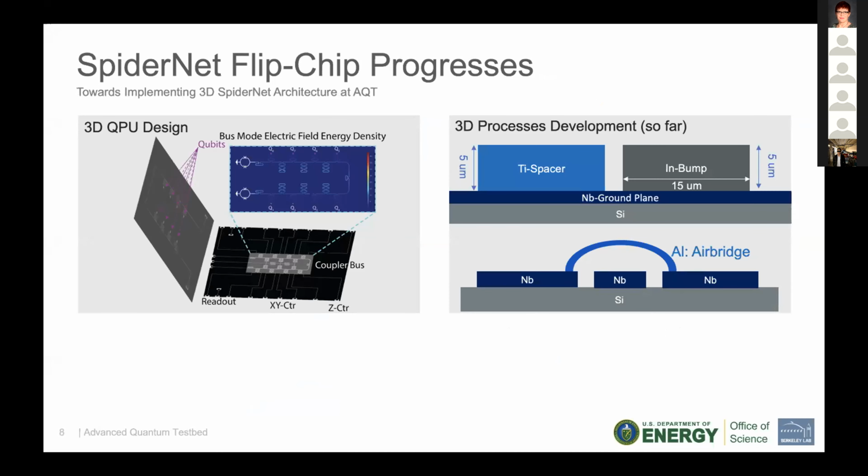So you can simulate the 8th order mode, the high order mode of this bus that we use to mediate the coupling between all the 8 qubits, in this blue box above. And you can plot out the voltage profile along its distance schematically with these black lines. You can see that we strategically placed all the 8 qubits at the voltage nodes of this voltage profile of this high order mode of interest.